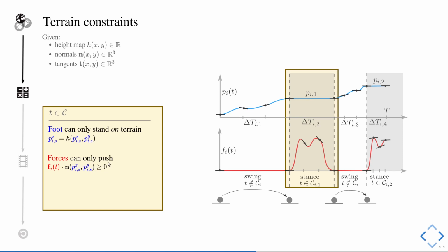So this is a very natural formulation, and it's equivalent to the formulation of keeping the center of pressure inside the support area, or the ZMP inside the support area. This is the same physical restriction that's modeled through these constraints, but here you can see a lot more directly how this relates to the physical laws.